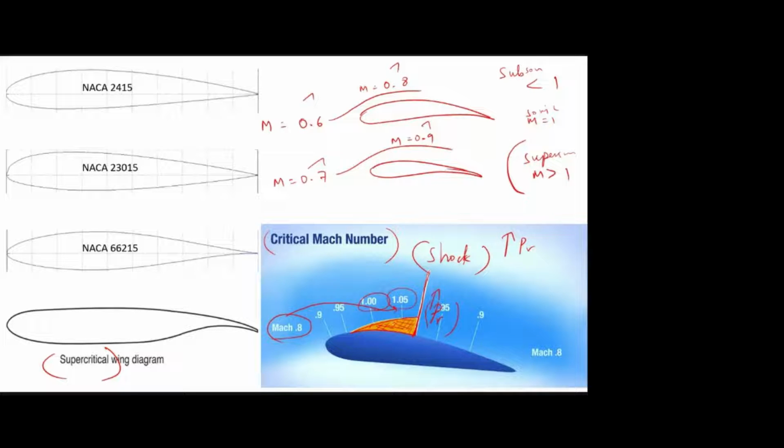Okay, so here supersonic, better acceleration, and so we are getting the shock wave, and behind the shock wave the pressure is very high because the shock wave is a compression wave. So here we have very high pressure, and here we have the free stream pressure, the atmospheric pressure, which is low, and due to this pressure difference there is an additional drag that is called wave drag.